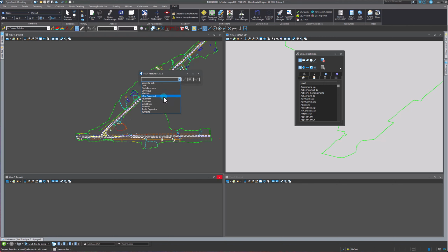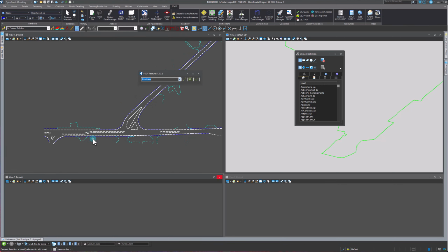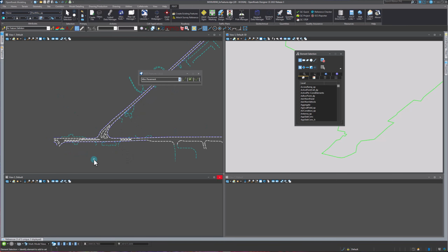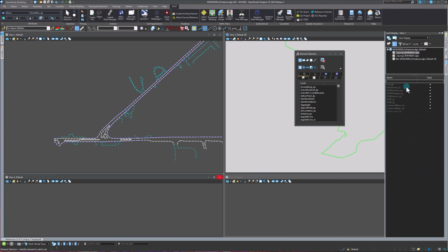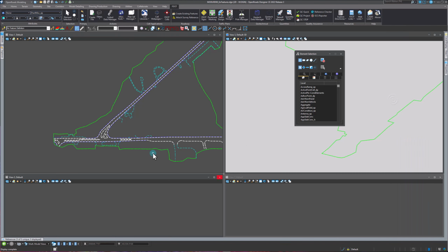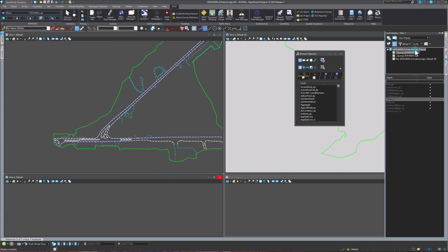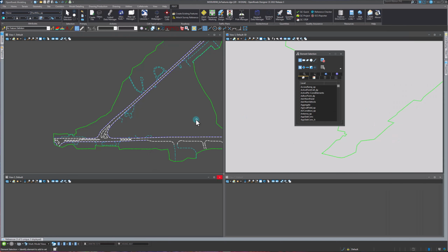So in this case, we're probably going to start with the pavement. I'm going to do shoulders just because that will leave the shoulders and this miscellaneous asphalt / driveway on. We could even come in here and do miscellaneous pavement just to make sure that's on as well. And you can see that's just applying a filter to this file to turn certain things on and off. So unfortunately, it does turn things off that we might want to see, like our terrain model. And it will start turning off things live in this file, so be aware of that as well.